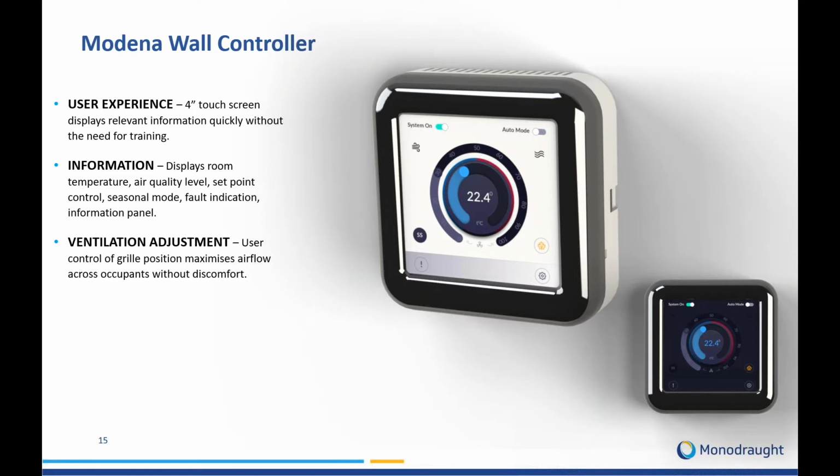So we actually developed a completely new wall controller. So it's a 4-inch touchscreen. This has 4 temperature sensors mounted within it, as well as a CO2 air quality sensor. And that enables us to get a very high accuracy level on the temperature reading. And it also provides that ability for us to give user information. So rather than having panels stuck behind wall controllers where people are trying to understand how they interact with a ventilation or building services, we're able to incorporate that within the screen.